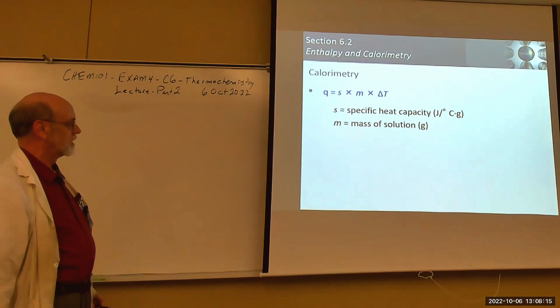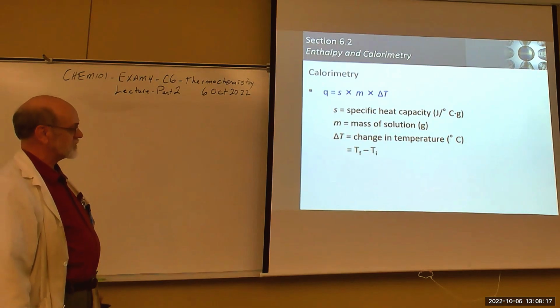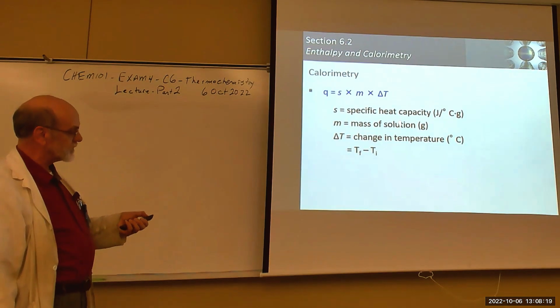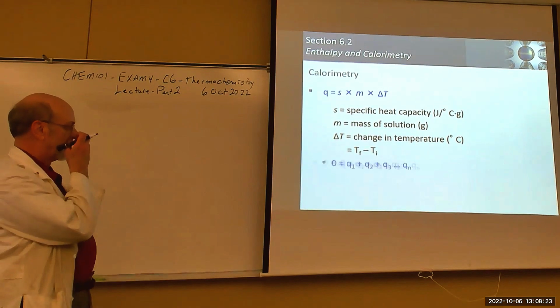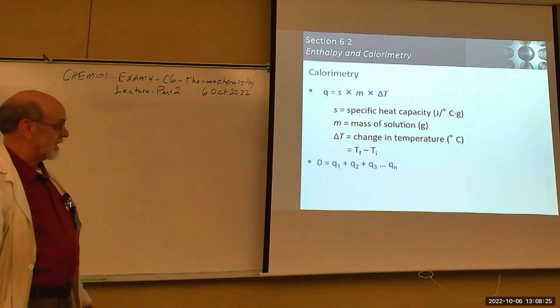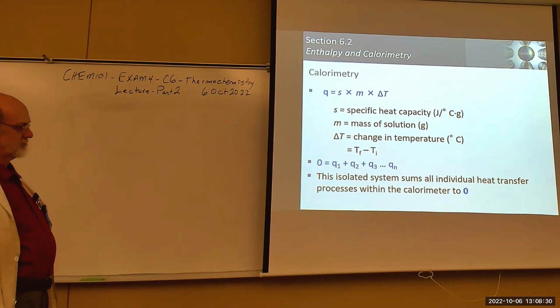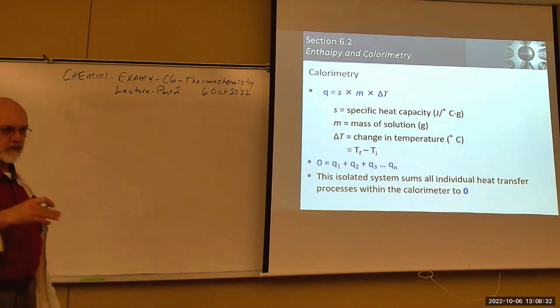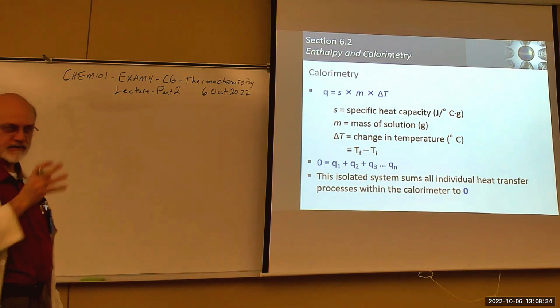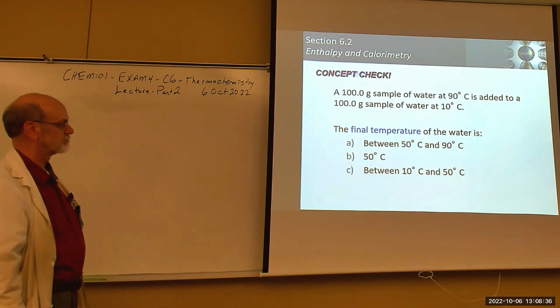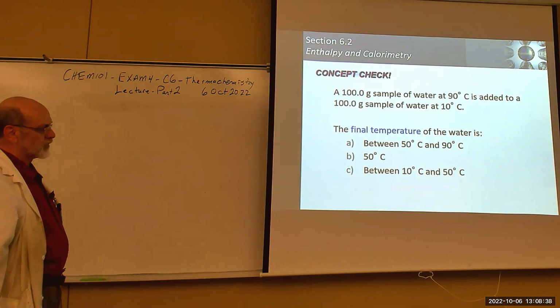There we go. Right, mass times change in temperature, final minus initial, always the order of things. And there's your generic calculation. Every heat transfer inside your isolated system has to add up to 0. We'll go through this one pretty quick.